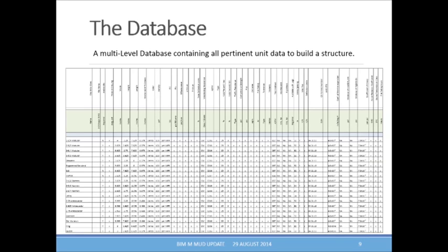So here we start with a database, and this is a multi-level. This is only one page, but here we maybe start with the size of a product. So I started with a 2 1/4 modular brick, and then we start looking at possibly, maybe a JPEG or a BIM three-dimensional model that's going to be attached to this. We would also have the issues about availability. We'd look at compressive strengths. We'll look at cold water absorptions if it's clay or concrete, or shrinkage, expansion. All those issues will go into here, and then behind this table there would be one for every different color or every product.